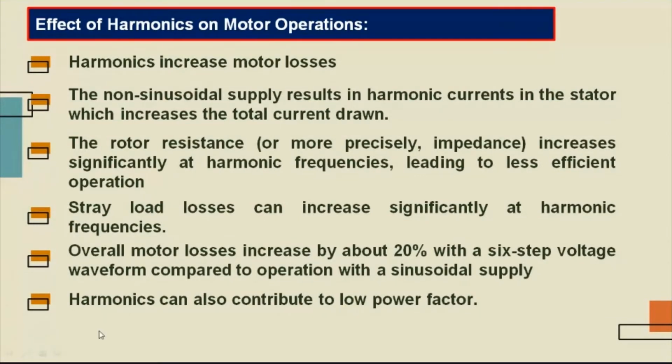You just have to remember that harmonics can also contribute to low power factor. That's why the mitigation of these harmonics, or minimizing the effect of harmonics on the motor operations, is very much essential if we want to achieve energy conservation on the motor side. So these were some of the points related to the effect of harmonics on the motor operation. I hope you all have noted them.